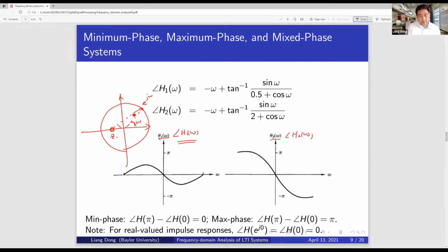If I am a point traveling from omega equal to 0 to omega equal to pi, then we will see an angle originally starting from 0. Then we get a non-zero number, which is negative, and we get the most negative part somewhere here. Once we reach the final point at pi, this angle also becomes 0. So it looks like that, going negative and then returning at pi. With similar analysis, we can plot everything. So the angle of H1(omega) indeed looks like that.